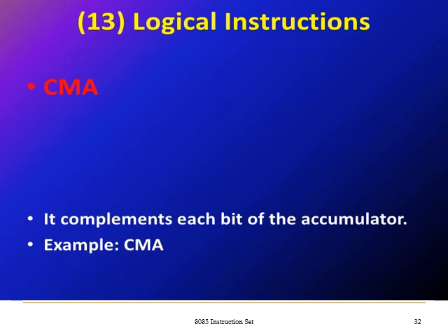The next instruction is complement accumulator, CMA. It complements each bit of the accumulator. For example, if you give CMA, the accumulator content is complemented. Each and every bit in the accumulator is complemented.